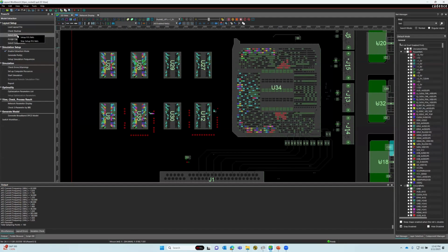Once your Stackup is ready, next you're selecting your nets. When you select your nets, you'll get a net list over here. The tool needs to know what nets to extract, what nets to focus on for the simulation. So you can come over here and select all the nets in the board that are of interest to this interface. In this particular flow, I've got the VTT shape because I want to include my terminations for my address bus.